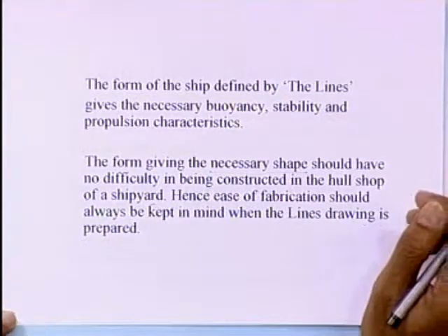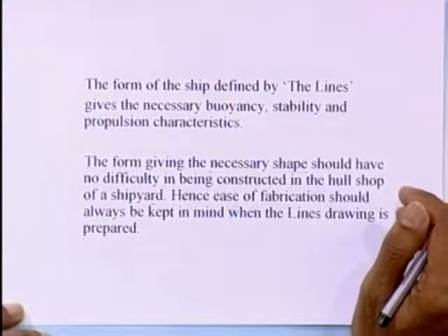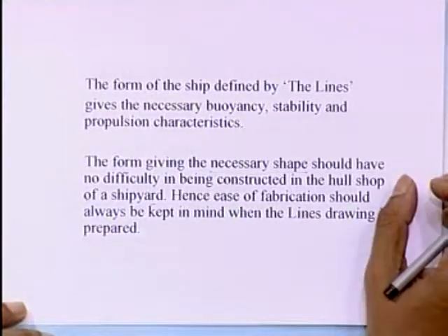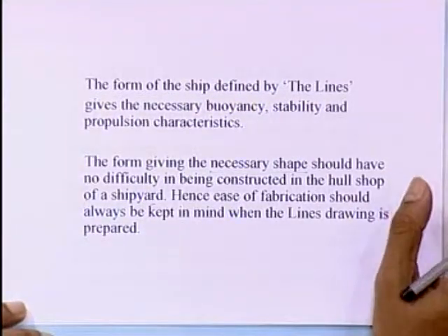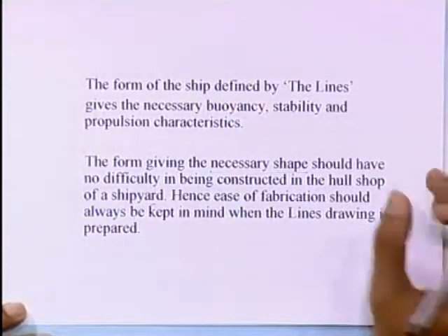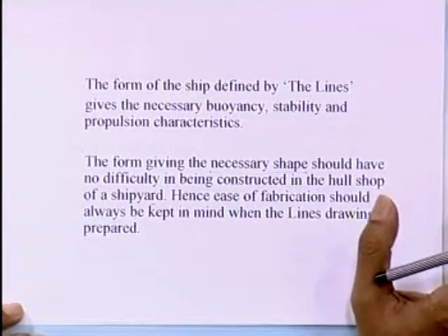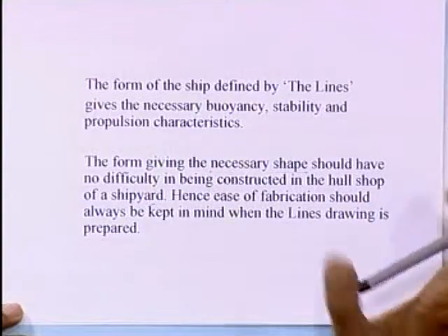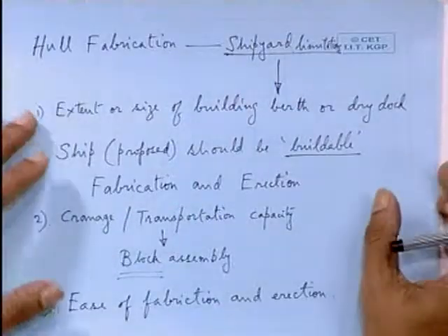In Hindustan Shipyard, I think some 20 or 30 years ago, they experimented with what is called the pioneer class ships, where the hull actually consisted of a number of straight plates, not bent. The hull curvature takes a lot of time: you have to bend the plate and shape the frames.